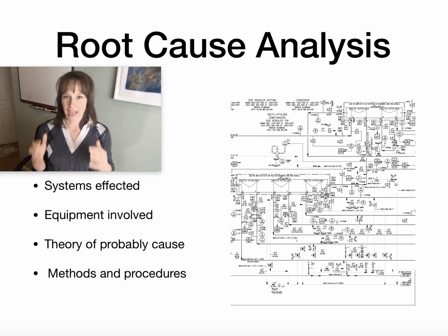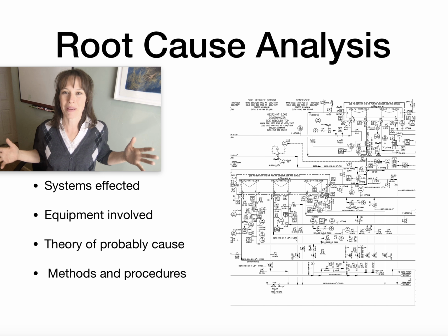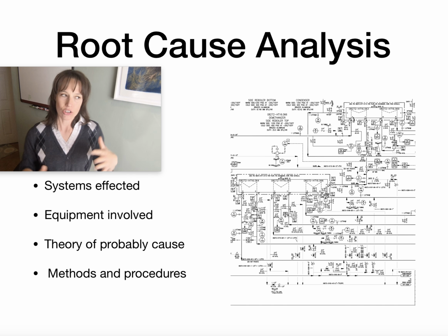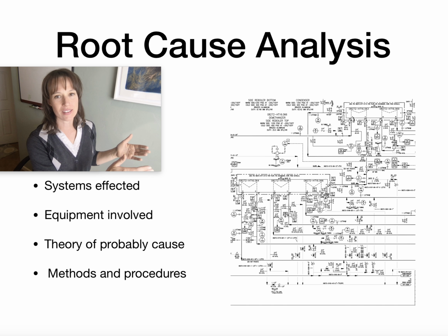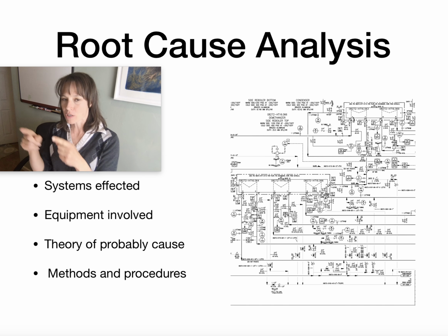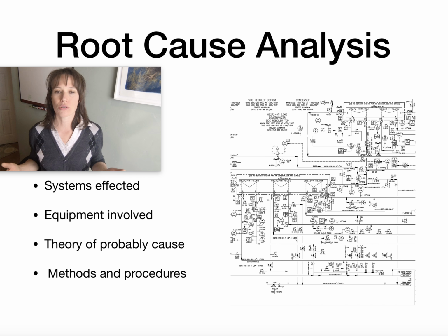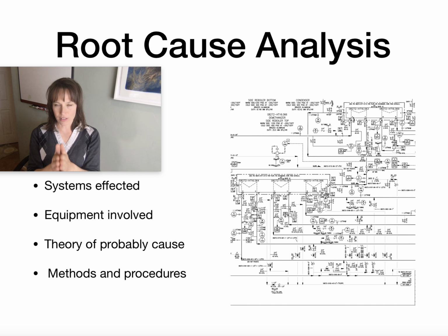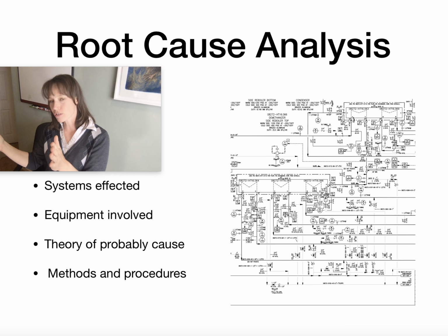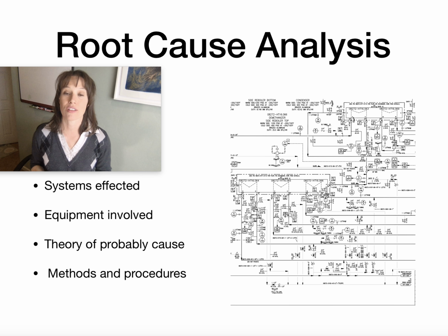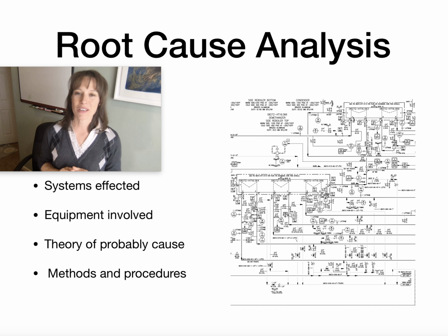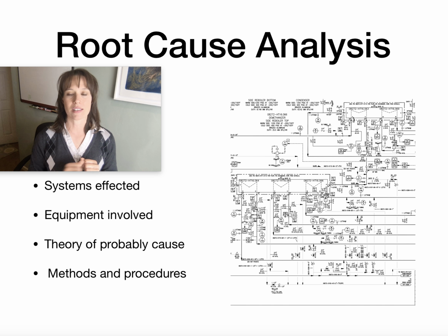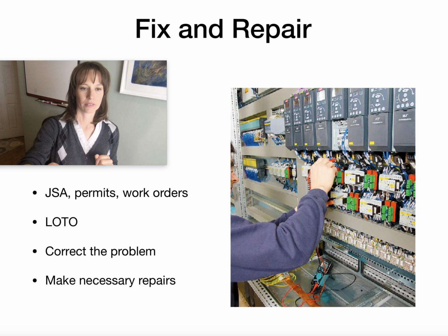If you have a large gas plant that has tons and tons of equipment and you know halfway in between, your compressor's down, you're not going to go to the very inlet of the system, start there and try to figure out which one it is. You may do a more half-splitting method. Is it upstream or downstream of half of this process? Okay, it's downstream. Okay, and then split it again. That sort of thing. That's something that I'll be going into in more detail in the root cause analysis module of this training.